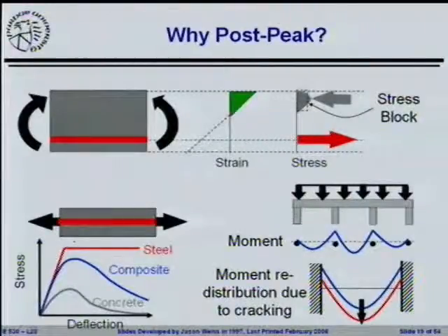They did an example that looked something like what we see up here at the top. They took a piece of concrete with some red reinforcing steel in it. They put it into flexure. They drew a strain section, right? They said, what happens if we start to put this into flexure? It's going to be in tension at the bottom. It's going to be in compression at the top. We assume the concrete doesn't do anything at the bottom. We assume all the compression is coming from the top. At the bottom, we've got all of our tension coming from our reinforcing steel. All of the compression is coming from the concrete.